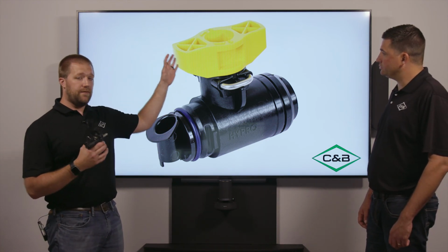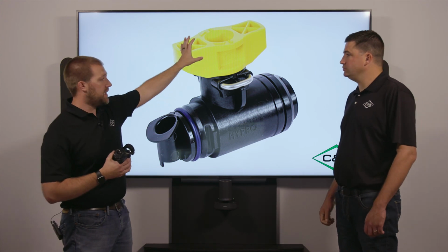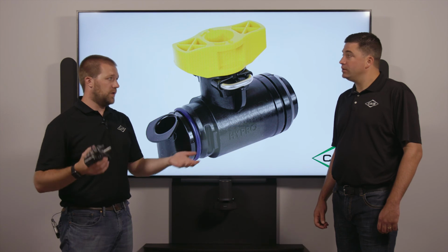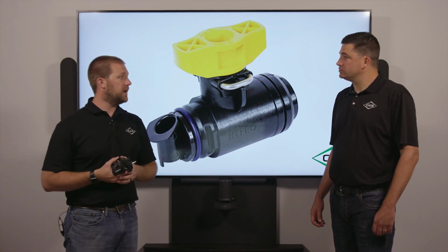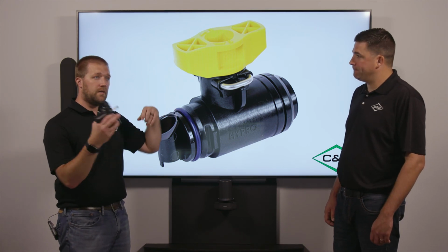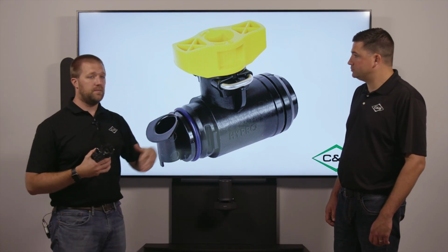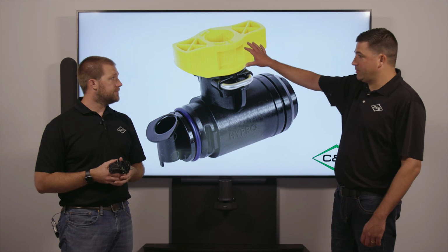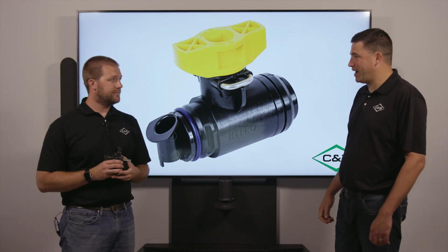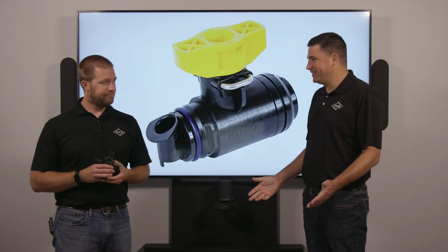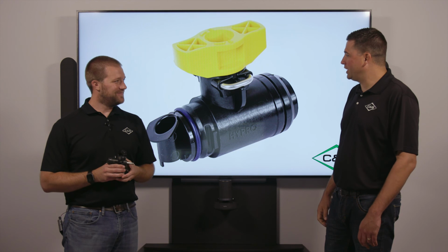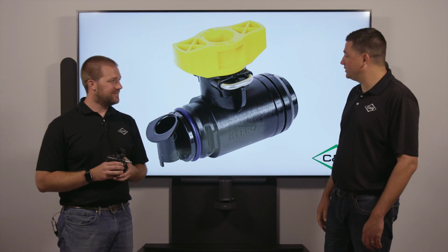But when you go to do a flush or a clean out, at the end of each section you've got a small valve. You can turn the valve and flush water out the end. You can rinse out your boom for 2, 3, 4, 5 minutes with a really, really quick changeover. And this is just pull the pin, take the cap off, replace it with this, and put the pin back in. Yeah, a lot easier to grab this handle versus trying to pull the pin or walk along with a screwdriver. Or if you drop the pin, you know, if you're on gravel, it becomes one of those OG moments, right? You know, to get that put back in. So that's real handy to have there.